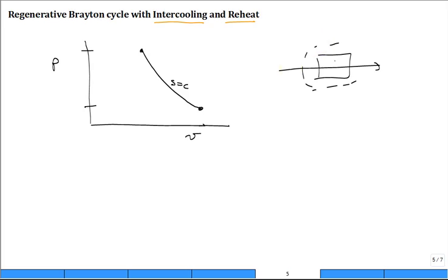That's the compressor. And we're coming in at state 1. We're going out at state 2 over here. And the goal is for the pressure at 2 to be high. Well, we worked out that you have to supply the work per unit mass, W dot per m dot, which is equal to the integral of v dP. Now, there's a minus sign, but I'm going to ignore that minus sign.